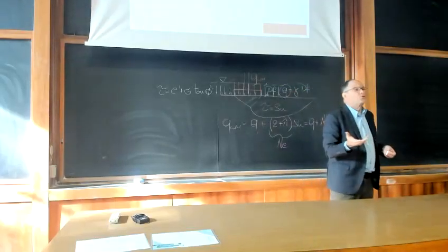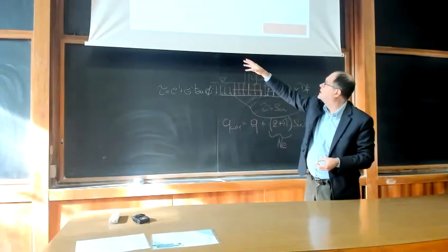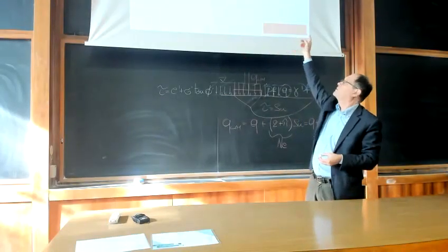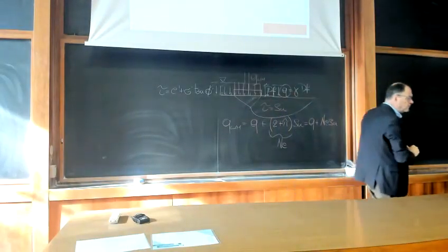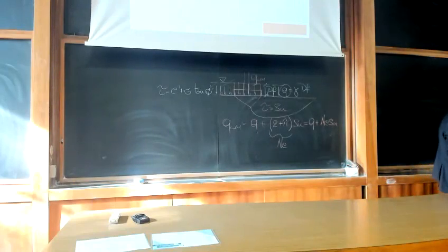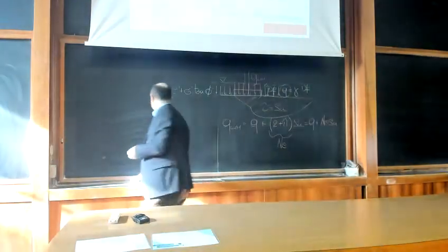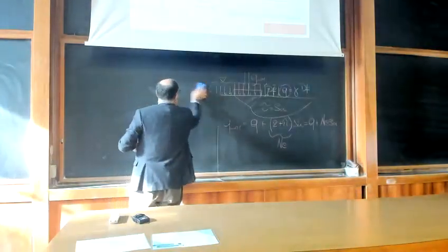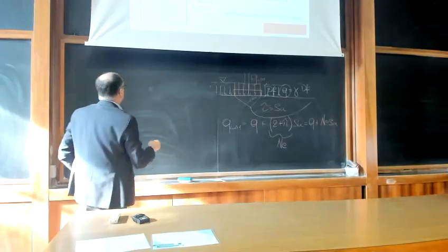We know how to consider the stresses according to Rankine theory, because we know Ka, we know Kp, and we can write the equilibrium on the right-hand side. Now, if you look at the horizontal equilibrium between the active zone and the passive zone, then you end up with an expression which is written on the right-hand side,